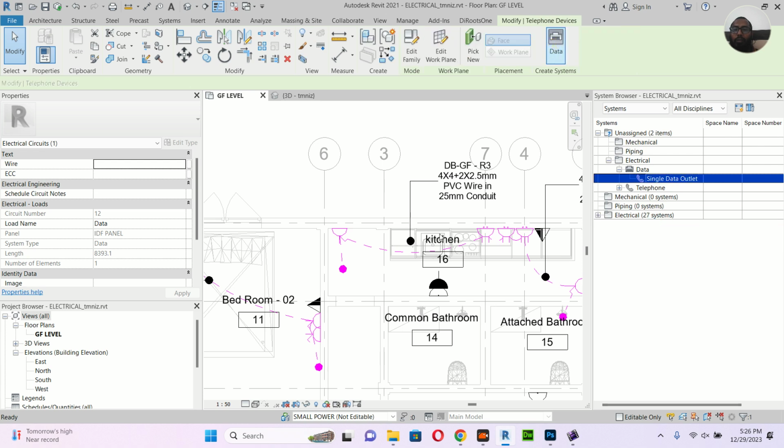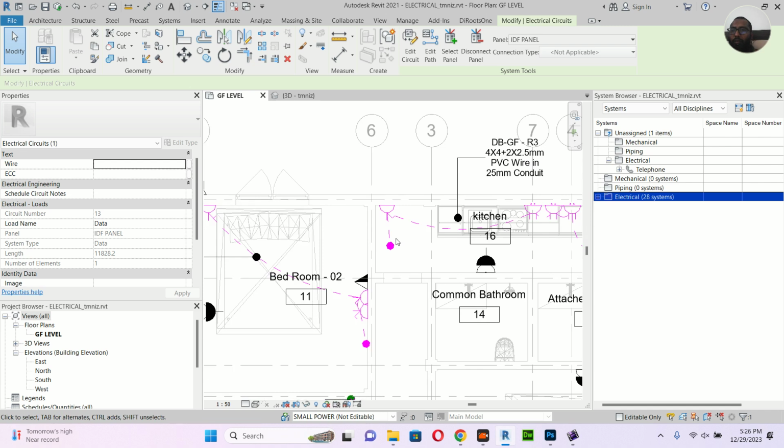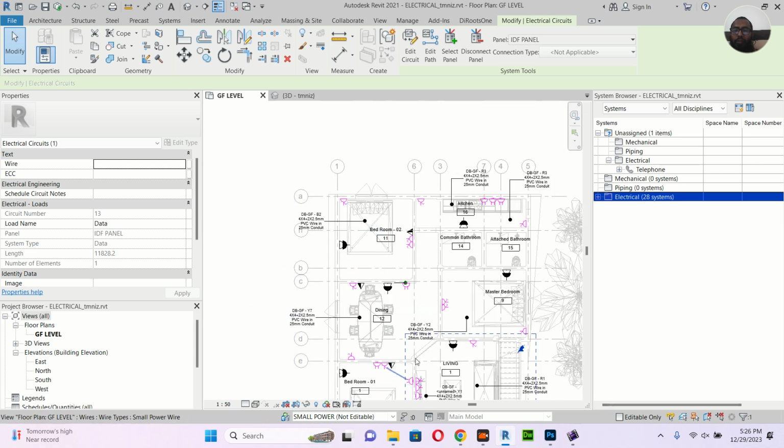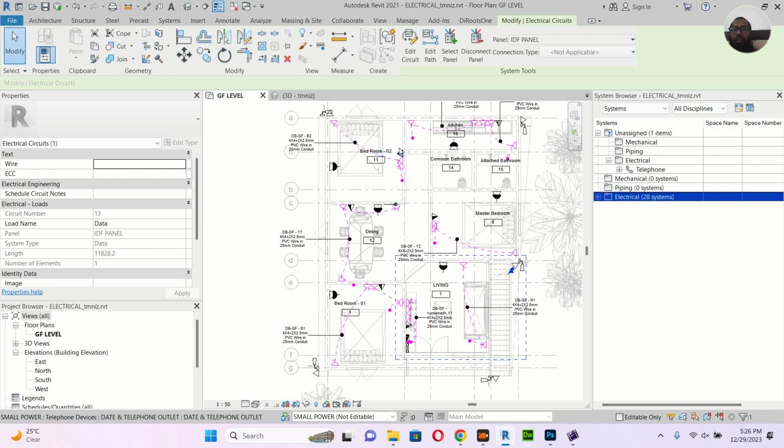And I hope you remember I told you we can use a Wi-Fi extender. After making that video, I remembered the Wi-Fi extender will connect directly to the Wi-Fi router. So you can run one cable from the main Wi-Fi router to the data outlet, and use a small, cheap Wi-Fi router that only covers the room. Let's say your main Wi-Fi router is here and the Wi-Fi is not reaching up to here. You can pull the cable up to here, use the cheapest router and cover this area. Also, this twin outlet has a telephone, which you can use for the intercom system.